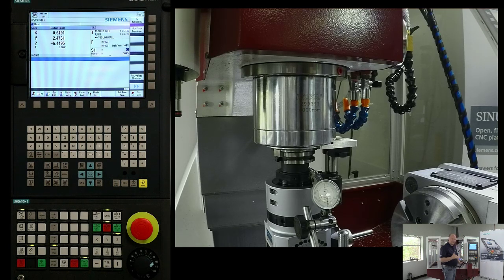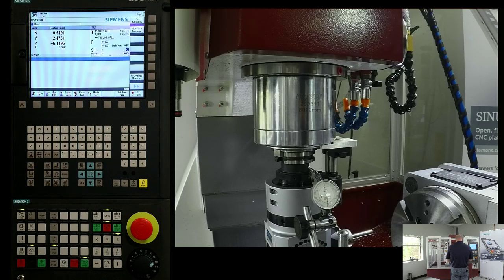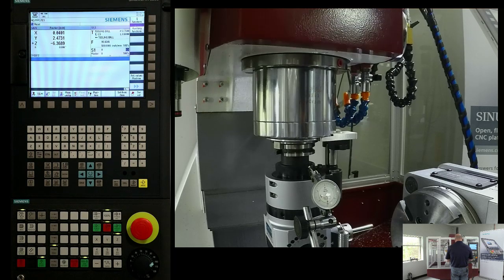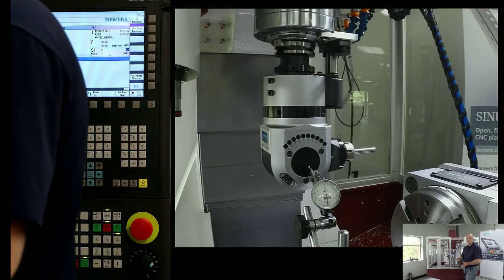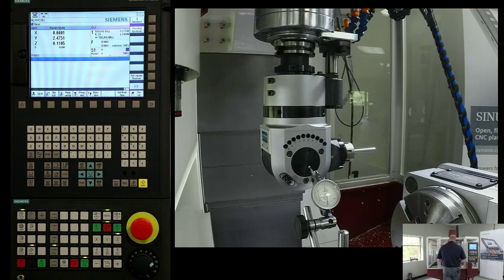So we previously measured that value, and that value was measured in at 7.0838. So that's an important number. So I wrote that number down because I need to know that value. So now step 2 in getting my dimensional values, and the manufacturer of these heads will give you these numbers, but you're going to want to at least double check them, because depending on how accurate those numbers are when they gave you, or you can just simply measure them on the machine.